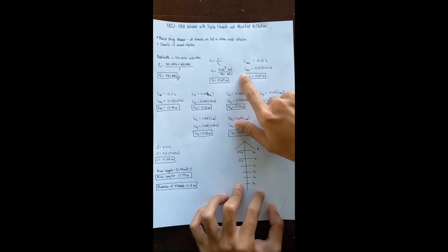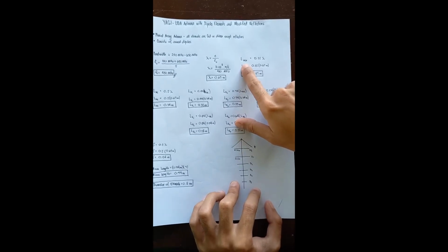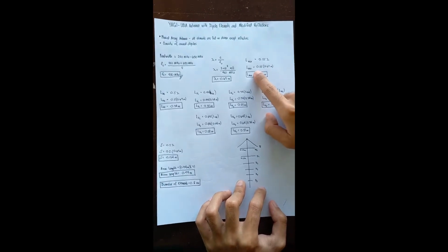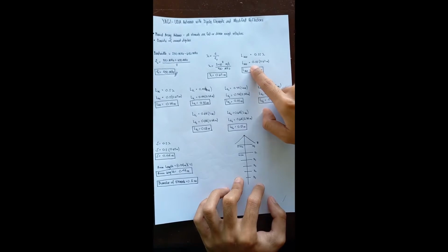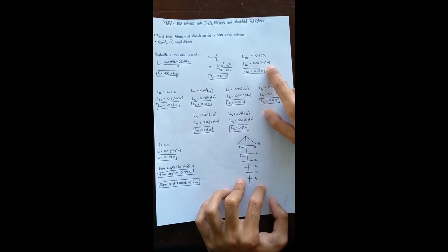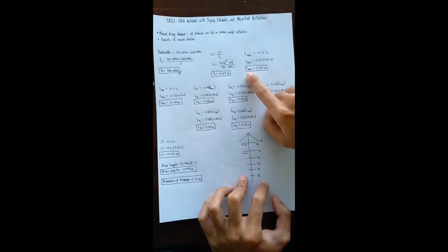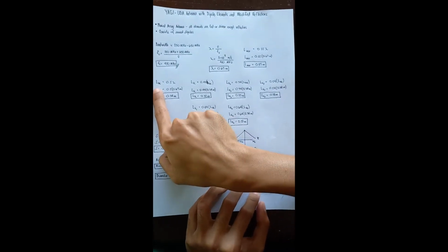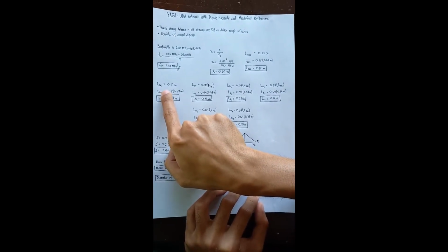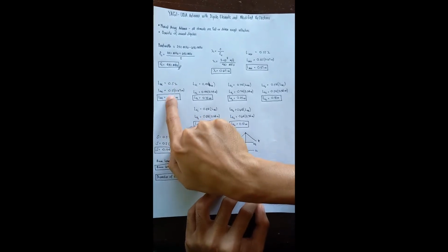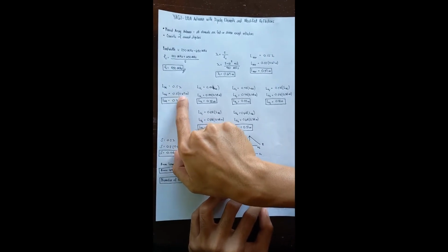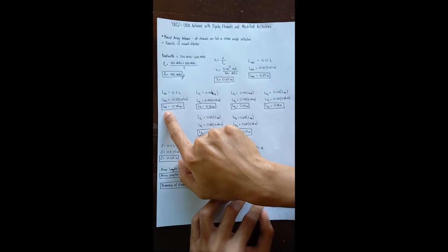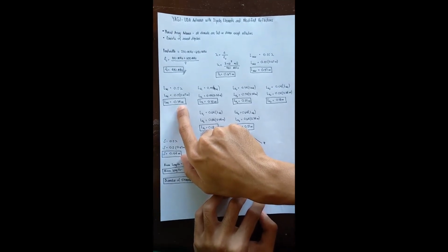Now we can solve for the length of the reflector, or H reflector. That is found by 0.55 lambda. We substitute the value of lambda, so we have 0.55 times 0.67 meters, and the length of the reflector is found to be 0.37 meters. The length of the driven element is 0.5 lambda. Substituting, 0.5 times 0.67 meters, the length of the driven element will be 0.34 meters each.